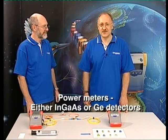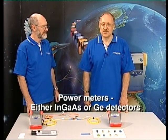Single-mode testing is more accurate and repeatable. It uses equipment fitted with laser sources at typically 1310 nanometers and 1550 nanometers, and power meters using indium gallium arsenide detectors or germanium detectors.